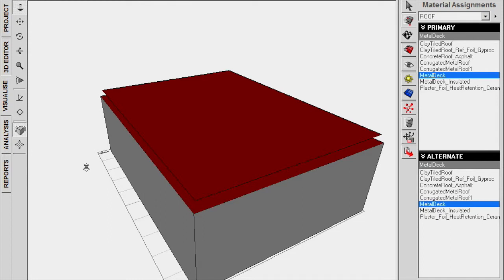Even if you're going to reshingle your house, it needs a new roof, and you're choosing different shingle colors, that has a huge impact. If you choose black shingles, they absorb a lot more energy. You have a very hot attic, which can be good or bad, again, depending on what your temperature profile is. If you have white shingles, they're going to reflect an awful lot. So color's huge in terms of what's going on.